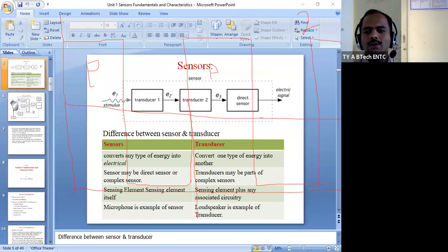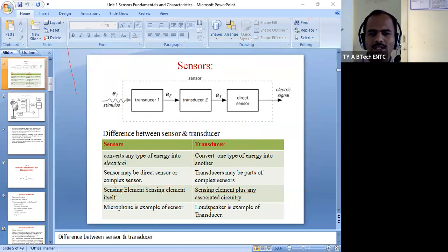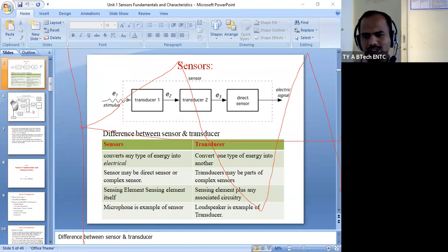Rectangular wave, square wave, similar case is there; again triangular is also there. Each and every type of waveform is just like this. The shape is not exactly this, just understand. For any case, cycles are there, positive as well as negative. So accordingly, you have to measure how many times the positive peak appeared and how many times the negative. Any one is also sufficient. If you measured first positive, then second positive, you just consider that 1 cycle. Are you getting, Sagar?